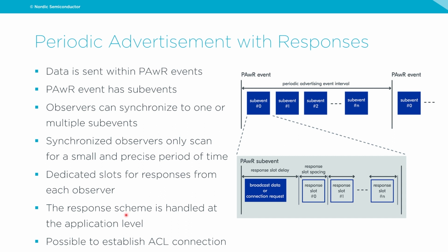The response scheme, or how you assign these responses to different observers, is handled at the application level. So on the previous slide, I talked about how ESL has a profile that was introduced also with Bluetooth 5.4. That profile describes the response scheme for ESL. So if this is a feature that you want to leverage, you can look at the ESL profile and see how it's done there as a reference.